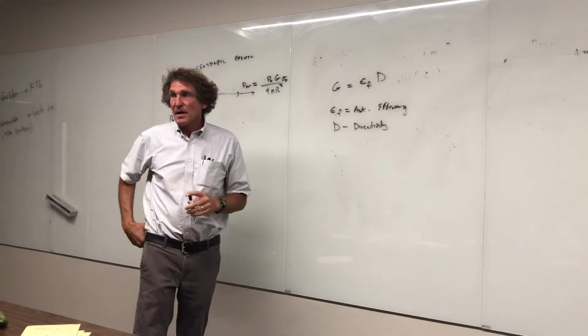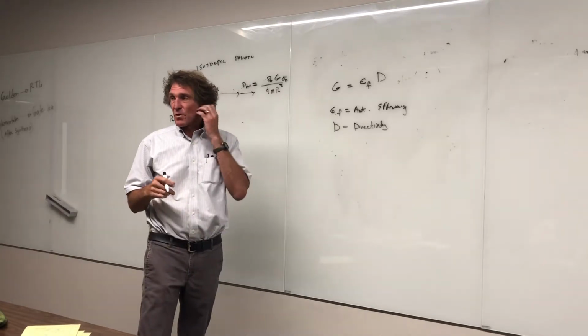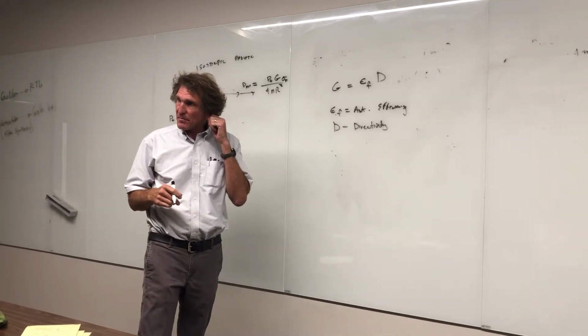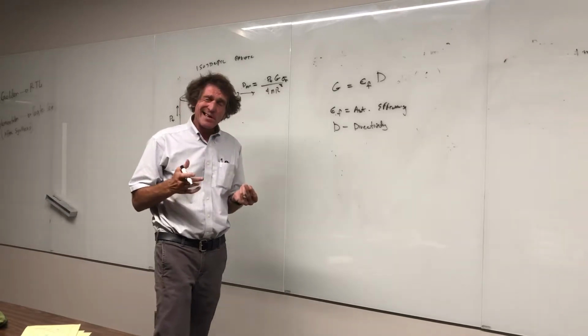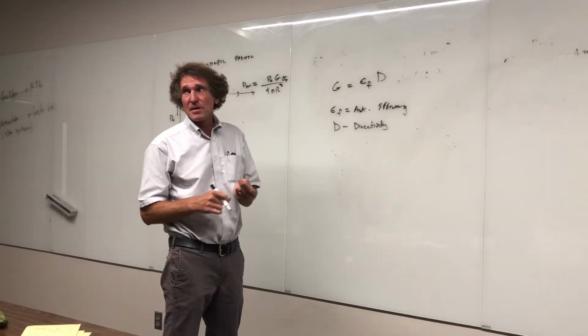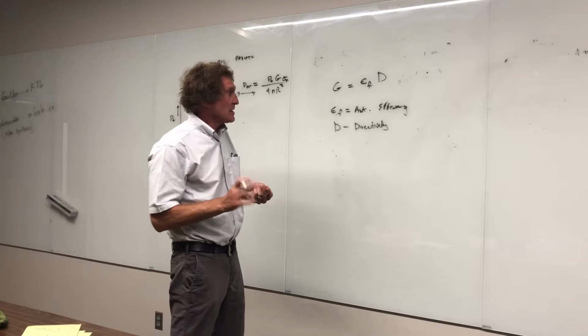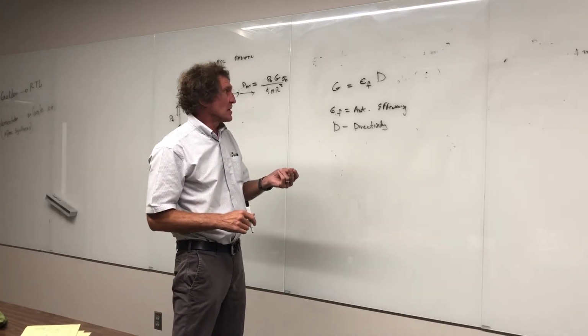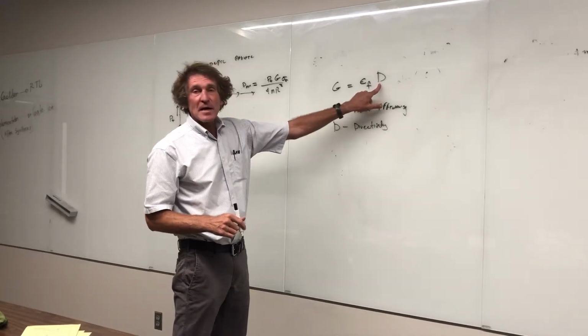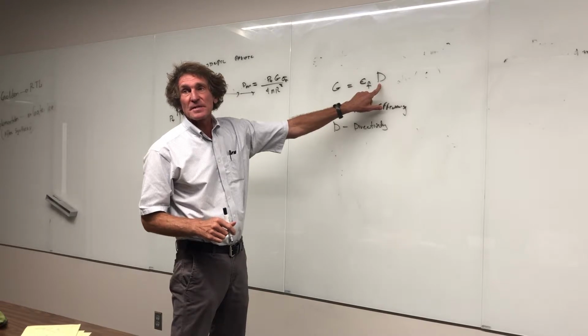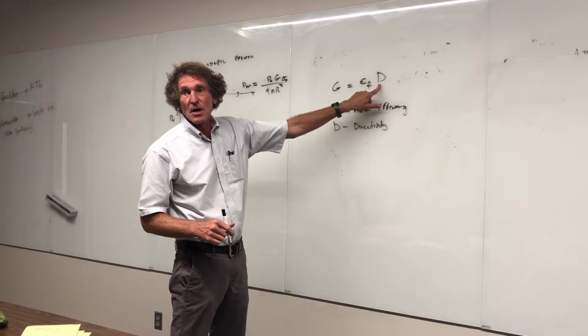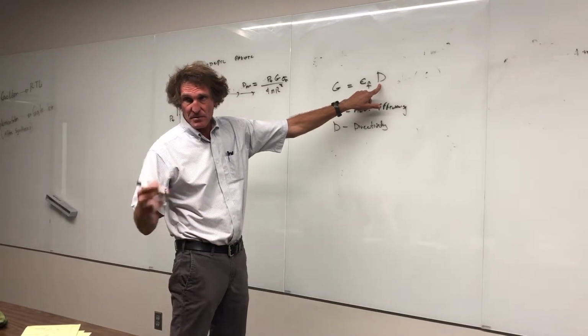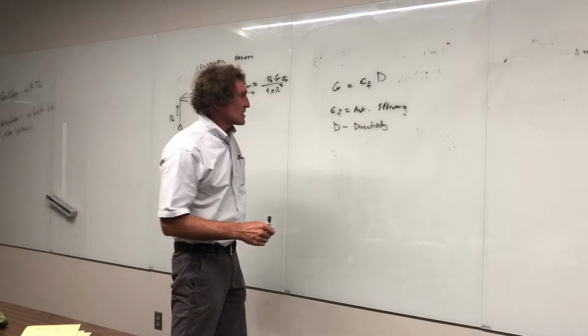But in some cases, where all of a sudden you have an extreme bandwidth at certain frequencies, you're going to have lower efficiency. It might go down to like 0.9. Then you have to be careful with gain and directivity. The directivity D right here is something that's calculated mathematically, and this is what we use for the calculations once we have the power density from a thin wire antenna. That's where we're going. So what is directivity?